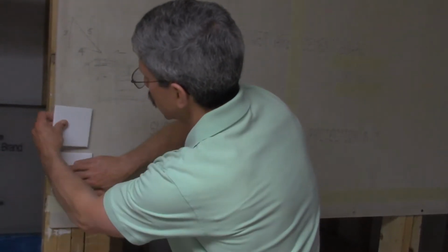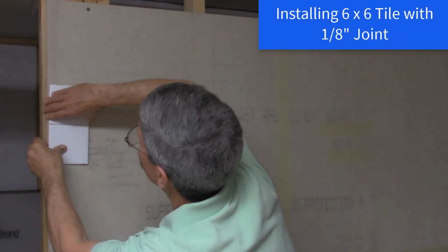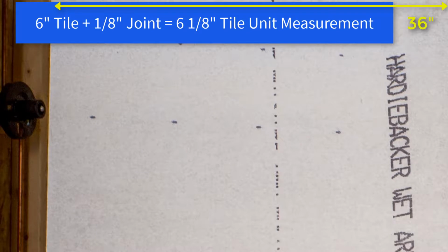For example, a wall measures 36 inches. The tile to be installed is a 6 by 6 inch tile with an 1/8 inch grout joint. The following calculation will need to be completed. Add the 6 inch tile plus the 1/8 inch grout joint. That equals 6 1/8 inch. This is the measurement to be used as the tile unit.